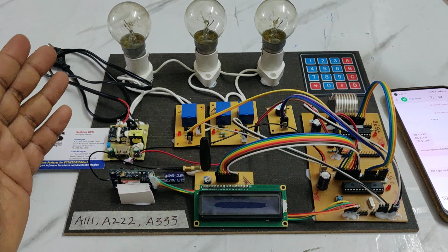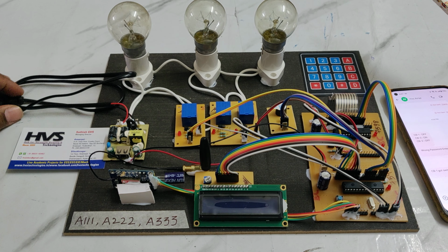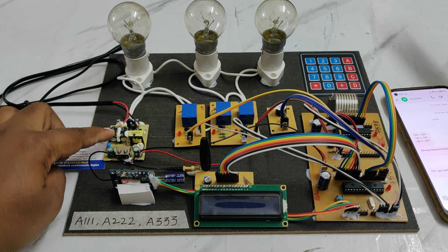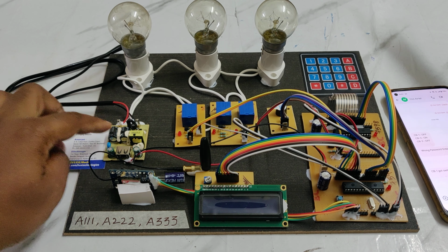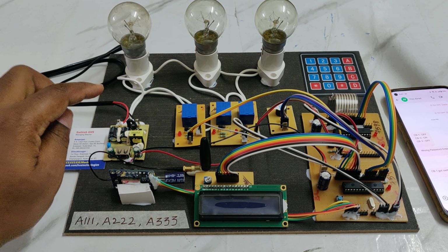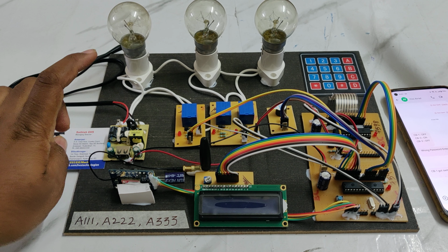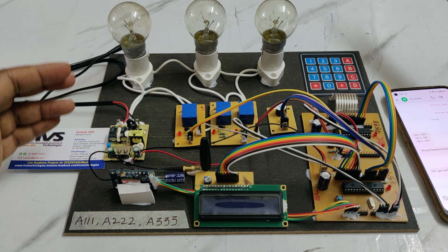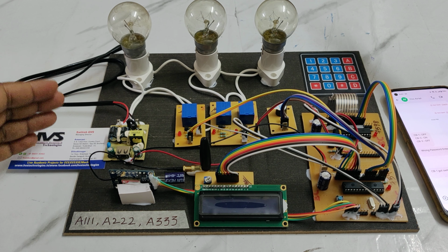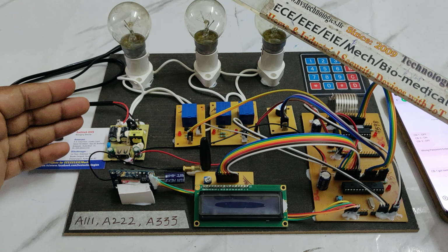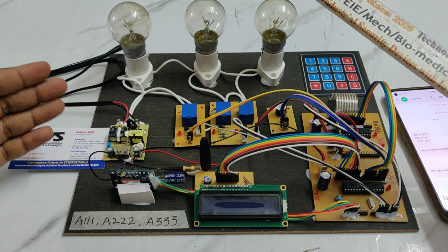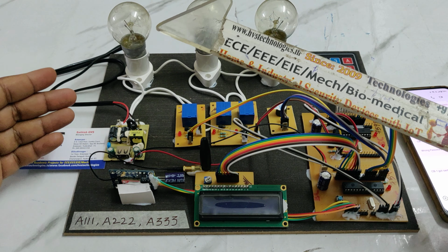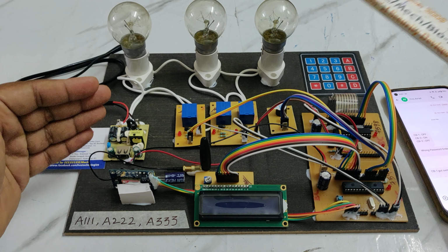To make these features work, the main power supply is 230 volts AC input to the regulated power supply board. When we provide 230 volts AC input, there is transformation, rectification, filtration and regulation. Transformation steps down the 230 volts AC to 12 volts AC, rectification converts AC to pulsating DC, filtration removes the pulses and provides us a pure DC of 12 volts, and regulation makes the 12 volts DC a constant 5 volts DC.